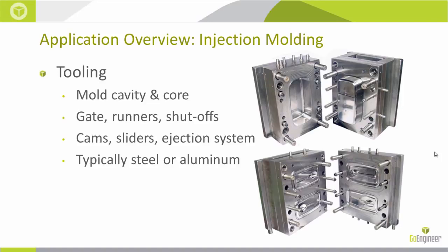We also have, say, cams and sliders that would allow us to come in from the sides or from the top, so we can get undercuts, so we can get very complex geometry inside our mold tooling.